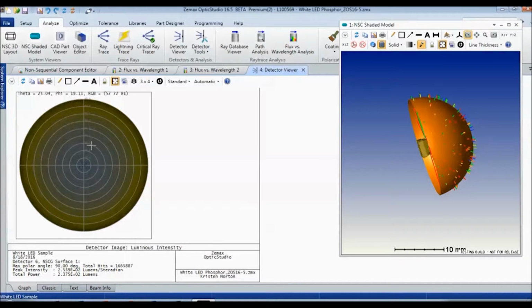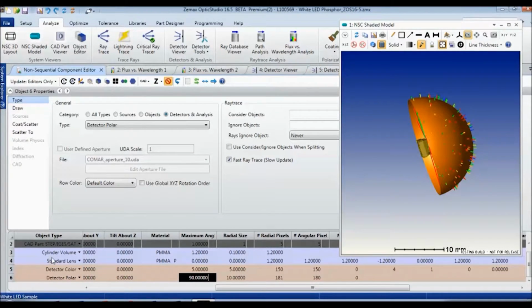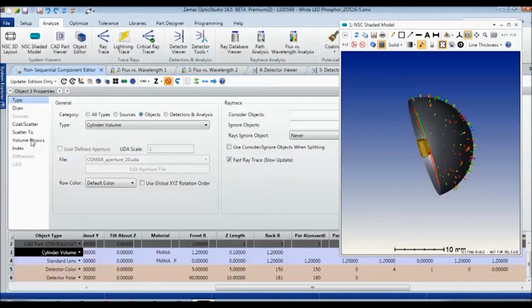In the middle, we can see a color distribution that looks more white because we're combining the yellow rays which have undergone photoluminescence with the unscattered blue rays which started from our source file. Then at the edges, we see more of the yellow rays which did undergo photoluminescence. I'm going to clone this window here and lock the original, so then we can view the new results on this other detector after we change some of the other photoluminescence properties here.